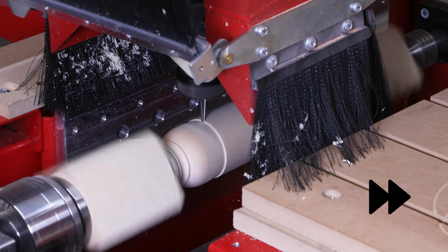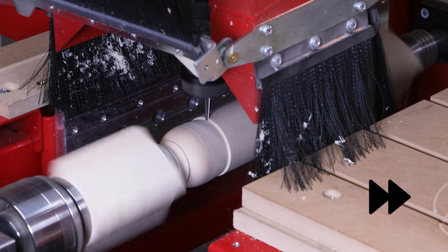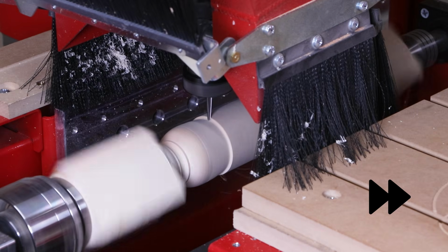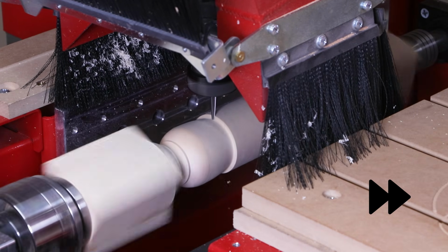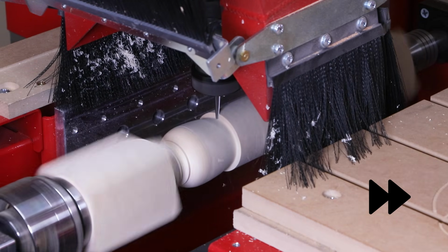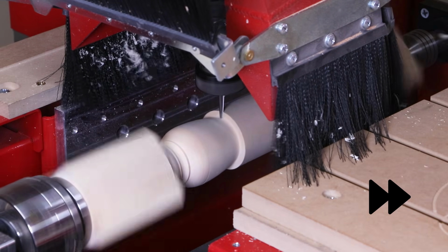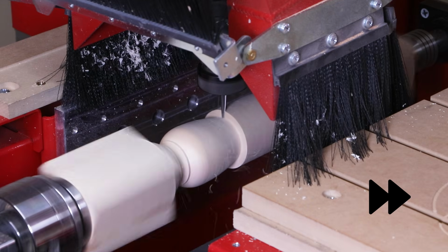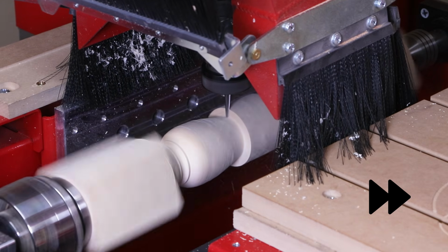One thing I didn't mention back in the designing and programming steps is that I like to program this specific toolpath from left to right, or from headstock to tailstock. The reason I do that is because this turning process is always going to rotate this in a clockwise direction. And so if we cut from left to right, it will actually perform the entire cut as a climb cut, giving us a much smoother finish.